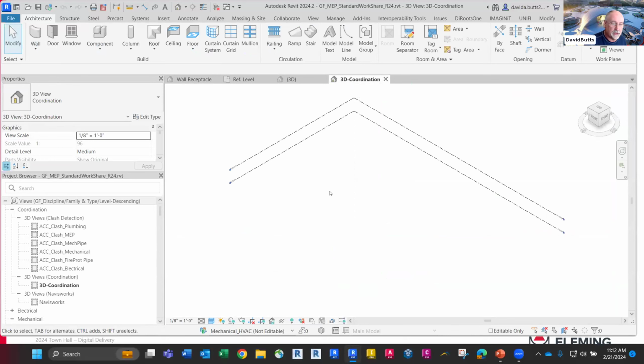This is another trick question for people in the crowd. Is everything hosted in Revit? Is everything you create hosted? The short answer is yes, because even a non-hosted element has a host, and that's the level it's created on. If you draw a wall up 50 feet and it's associated with the first floor level, it could be crossing second, third, and fourth floors, but its host is going to be the level it was created on. The same thing with lights and receptacles that are non-hosted: you want to be in a view that has that level, so that when you put in that receptacle, even if it's non-hosted and you adjust the height on it, it's still going to be hosted to that level.